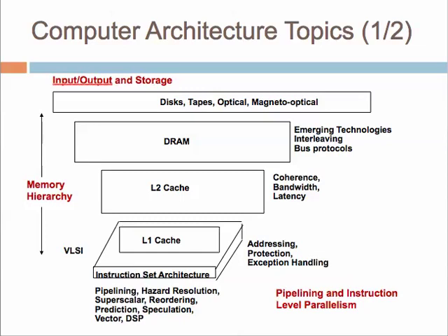Further, if you go in, you would see the DRAM. Now, the DRAM is your main memory. Today we already have solid state devices. You would look at PCM, which is phase change memory. So there are some emerging technologies that are coming, that are trying to replace the DRAM. Of course, most of these ideas are to combine these emerging technologies with DRAM rather than to completely replace it, because DRAM is a commodity device, and it's available and it's easy to manufacture.